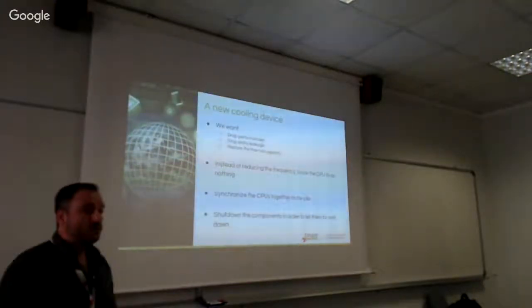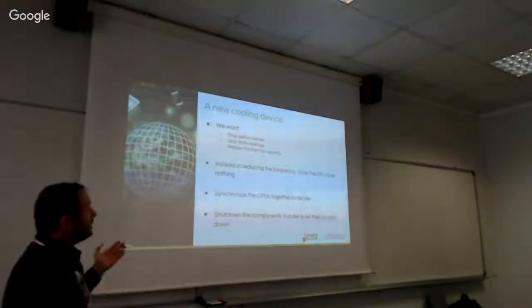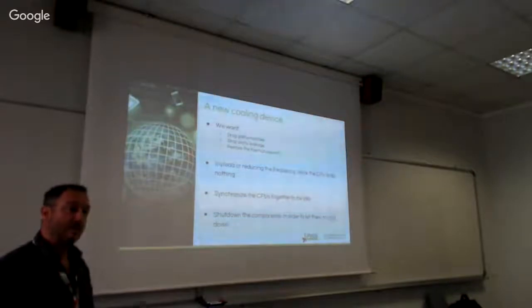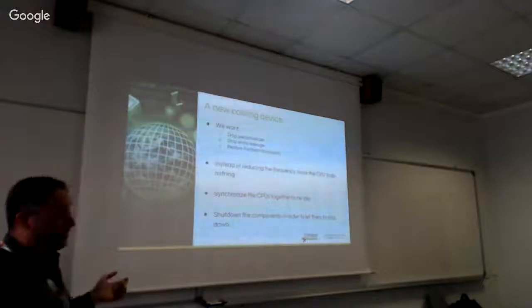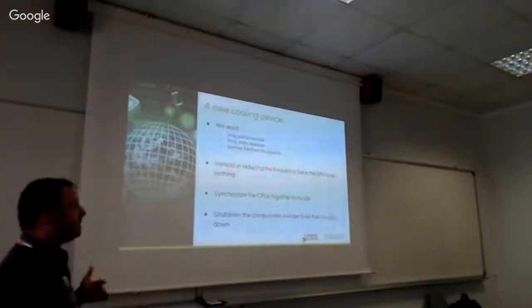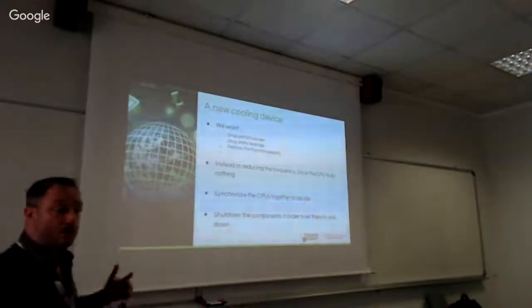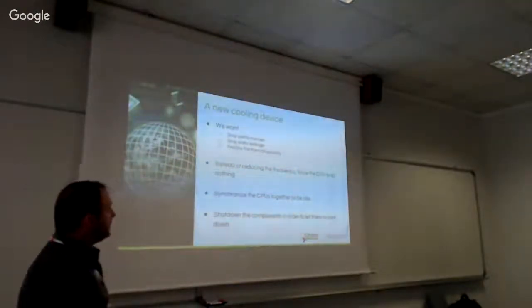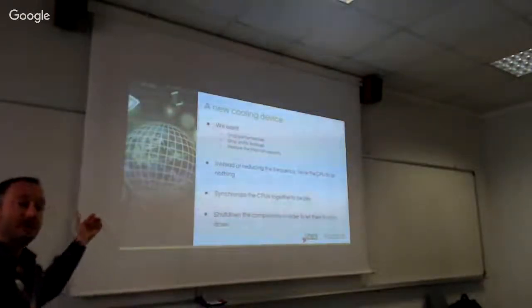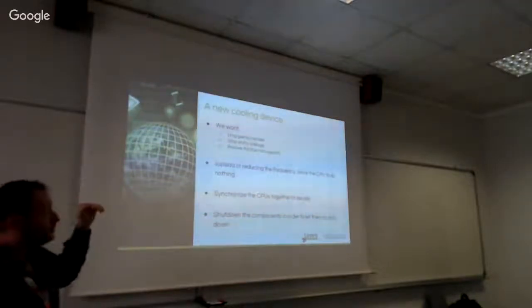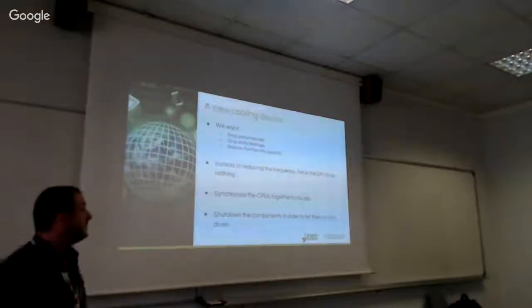So what we would like to do is to drop performance like cpufreq, but also drop static leakage in order to let the circuitry cool down, and be able to reduce the heat which was accumulated on the SoC. So the idea is, instead of reducing the frequency like the CPU cooling device is doing today, we want to force the CPU to do nothing for an amount of time.